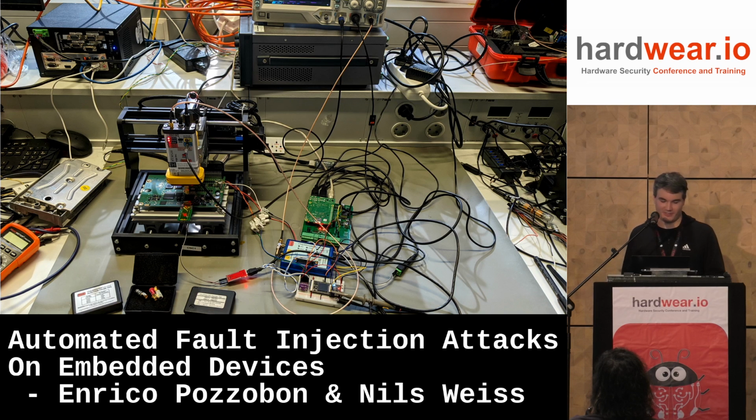So this is our first fault injection setup. Actually, no, this is not the first version, but you can see it's a nest of wires. We have a Raspberry Pi connected to some relays to turn on and off the ECU. We have a ChipWhisperer Husky to generate the delay from the trigger. We have an FPGA, some custom FPGA bitstream there, just to generate the trigger from the CAN signal, because we couldn't get a signal on a specific CAN message on the ChipWhisperer.